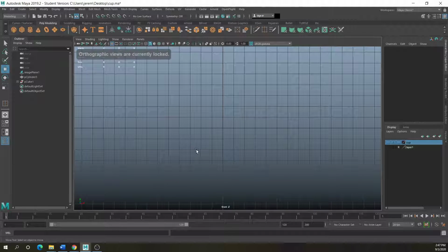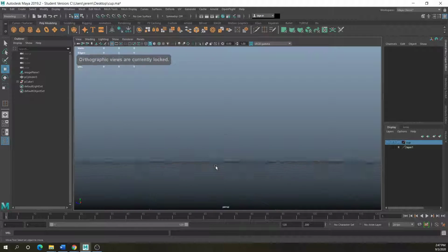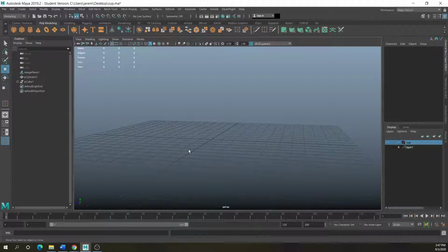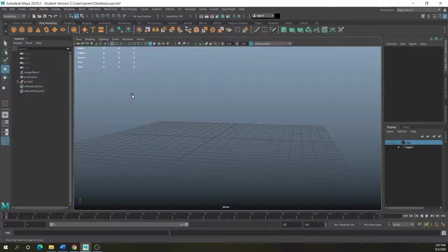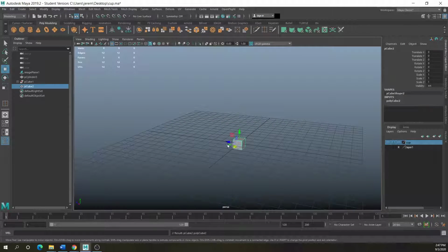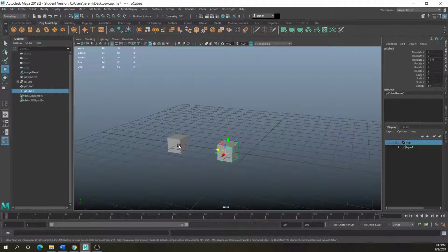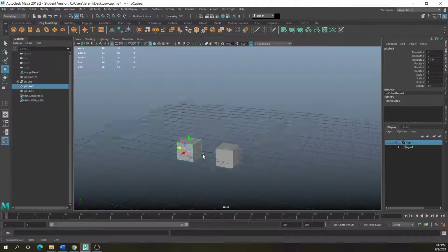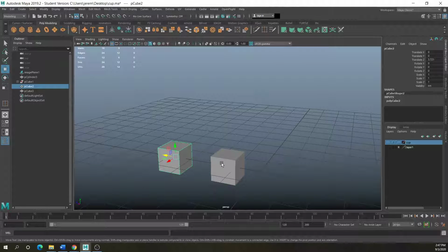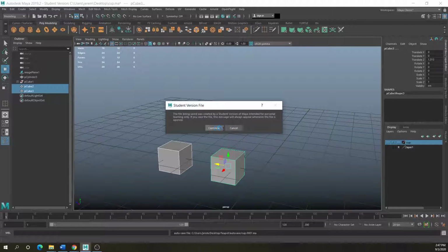Whenever we're going to create objects together, say for instance the cup that I just showed, you'd want to combine these two objects. We talked about that with the teapot, combining the curves together, grouping, but this is actually combining the meshes together. If we had two boxes here, duplicates, and we want to merge them together and work on them, like connect the faces or connect the vertices, you need to combine these meshes together. So you'd select both of them and choose mesh combine.